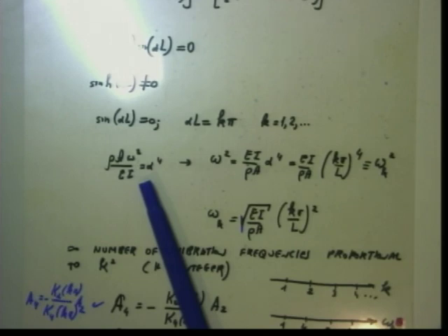Sometimes things are not in order naturally. It could happen when excitation is very specific. Suddenly we knew there is a resonance phenomenon, etc. Now there is more possibilities for resonance. If the outside frequency, the excitation, coincides not just with one frequency, but any of these frequencies, suddenly the response may go to infinity. Yes, it is more dangerous from that point of view.